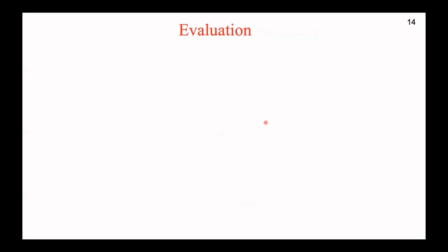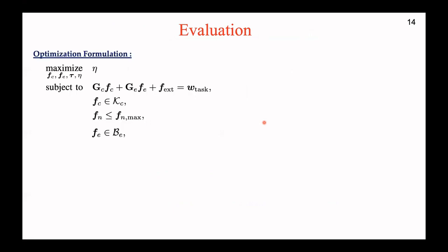As described in our previous slide, we are interested in computing the maximum amount of wrench that a grasp can generate along a given screw axis S. This serves as the linear objective function of our general optimization formulation. The friction cone constraints are second-order cone constraints, and all the other constraints are linear. Thus, our optimization problem for computing the task-dependent grasp metric can be modeled as a SOCP. In this paper, we have assumed that the manipulation is quasi-static, and therefore the inertia effects and dynamic forces are very small and can be ignored.